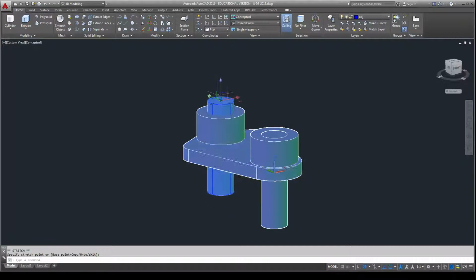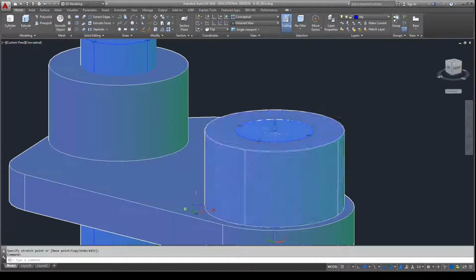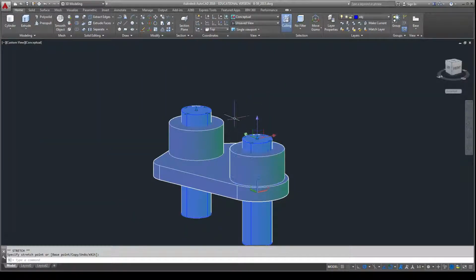So I'm going to use the 3D move tool. If I select an object, I can click on its grip and move it in the +Z with the polar snapping. And if they're passing through the object, I can use these. Escape to deselect. I can use these to cut holes in both the objects.